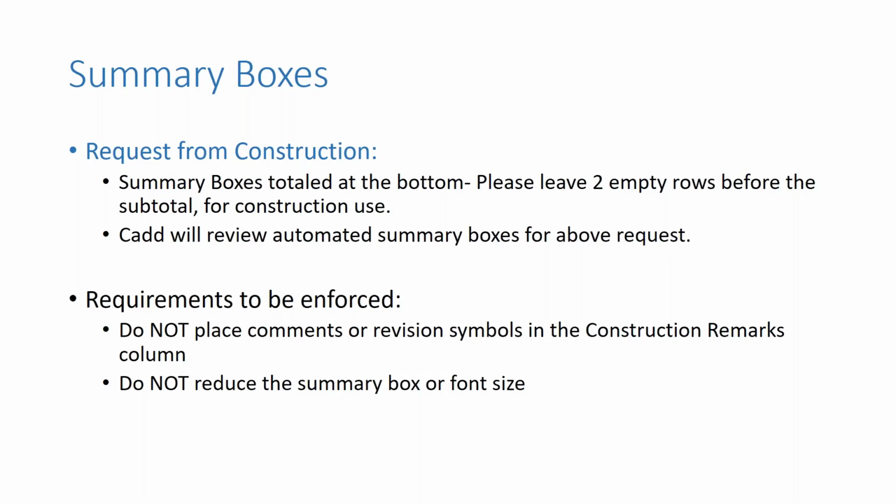Requirements that the construction office will also be enforcing: we do not allow any comments or revision symbols in the construction remarks column. Again, they need to reserve that space for the remarks during the construction period. Also, do not reduce the summary box font or the overall size of the box. While it may allow for better presentation on the page, it has caused issues with sufficient space for noting construction remarks and or revisions.